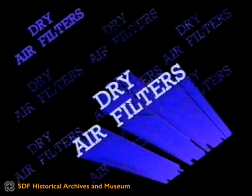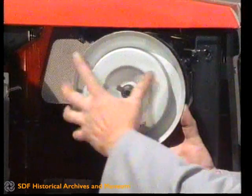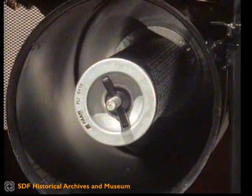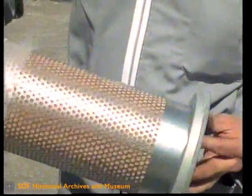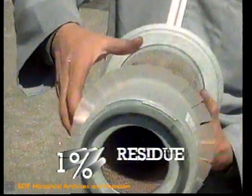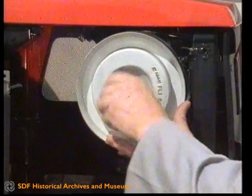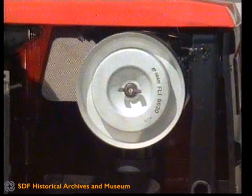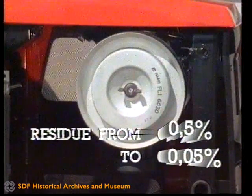Dry air filters. The dry air filters are preferable to oil bath cleaners since they provide better protection of the engine, with filtering efficiency from 2 to 20 times greater. The oil bath cleaners have a maximum efficiency of 99% with a 1% residue. Air filters have a minimum efficiency of 99.5% and achieve up to 99.95% with a residue of from 0.5% to 0.05%.